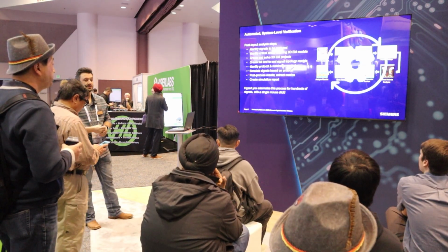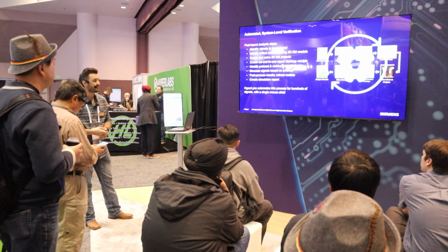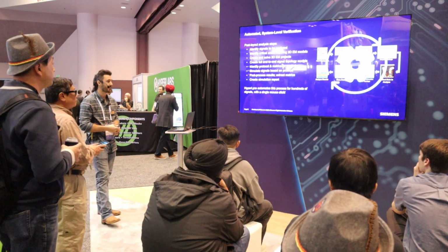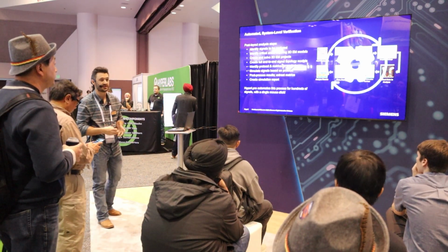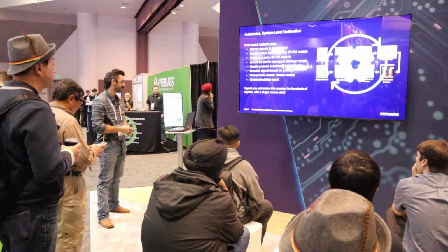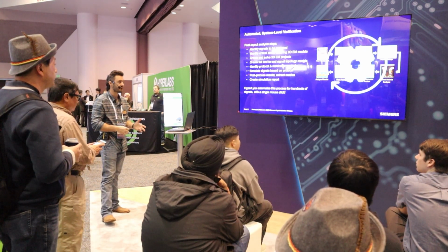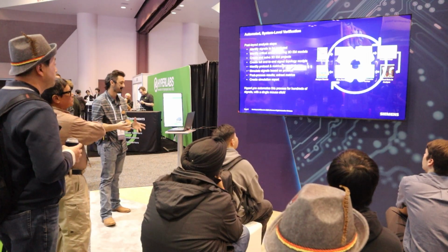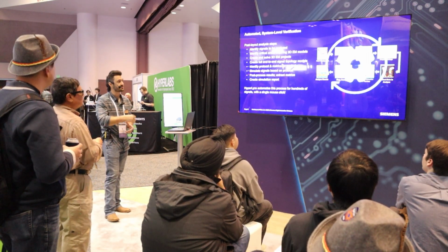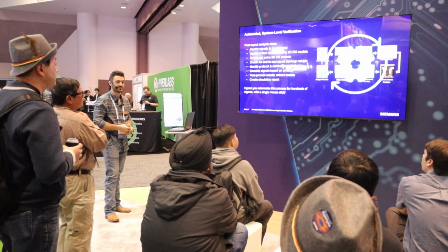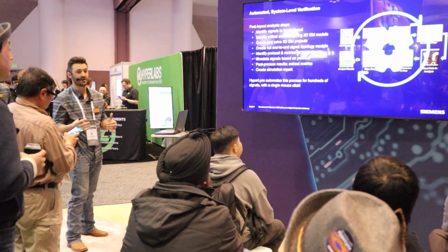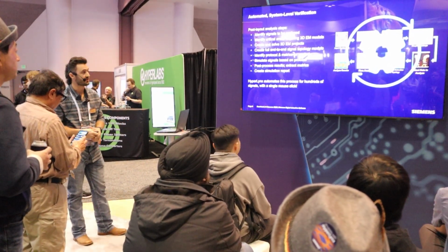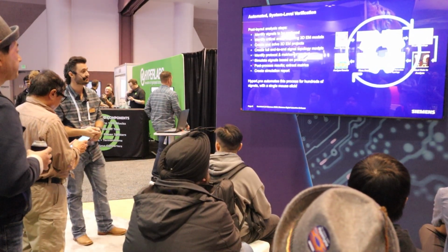We then simulate those signals based on the protocol, and finally move on to post-processing our results based on those metrics and creating any relevant simulation reports. That's a lot of steps and a lot of work, and it's usually impossible to complete this manually with any sort of volume. So with HyperLynx, we're able to automate this process from front to back, and we're able to simulate and verify hundreds of channels, including 3D areas, with a single button push.